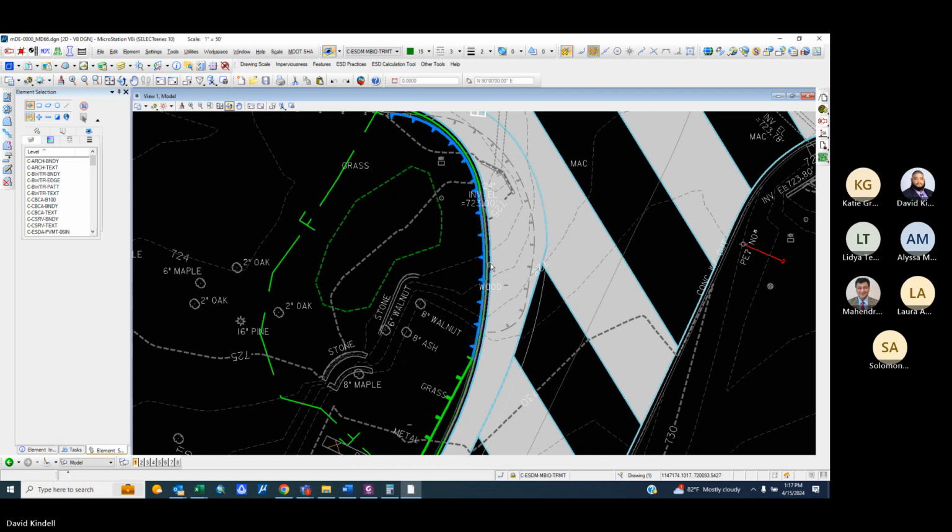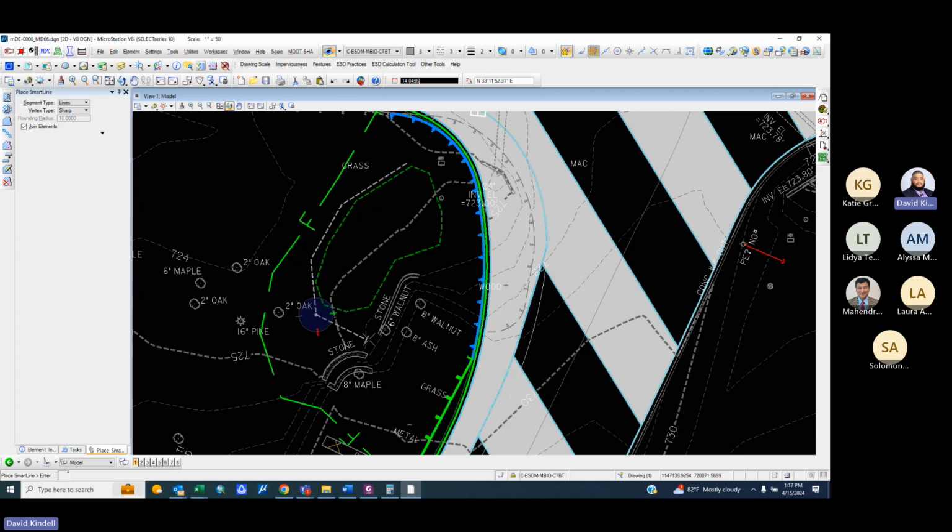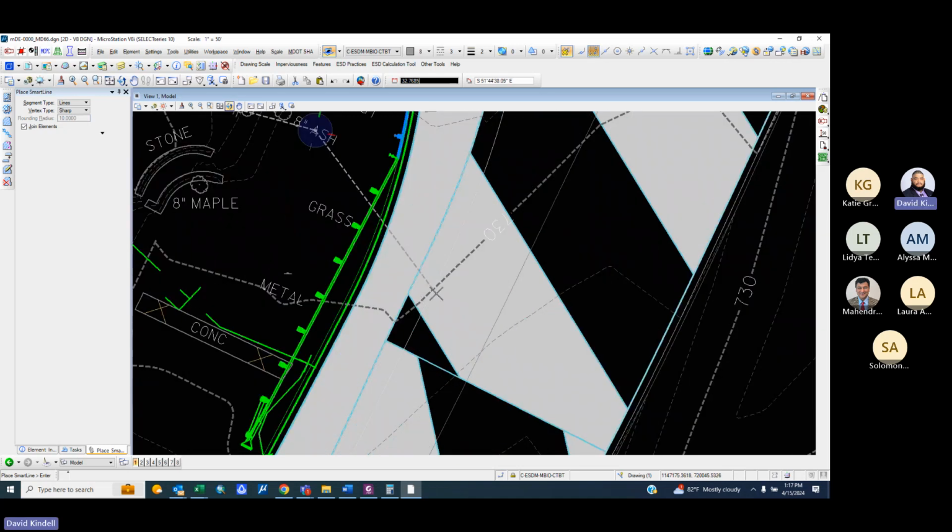So it'll probably be like a curb cut here. So that means if we imagine we're going to put a curb cut here, then we can delineate our drainage area, contributing area boundary. We just say okay, I'm assuming it'll go like this here.